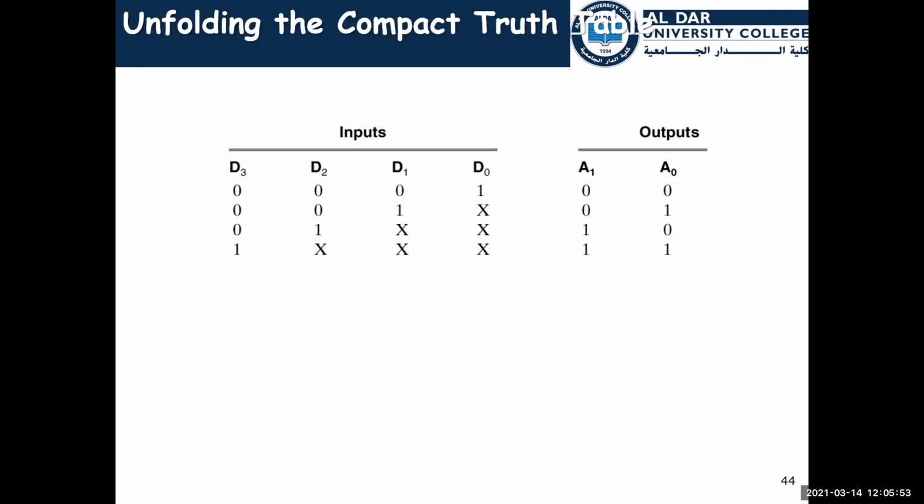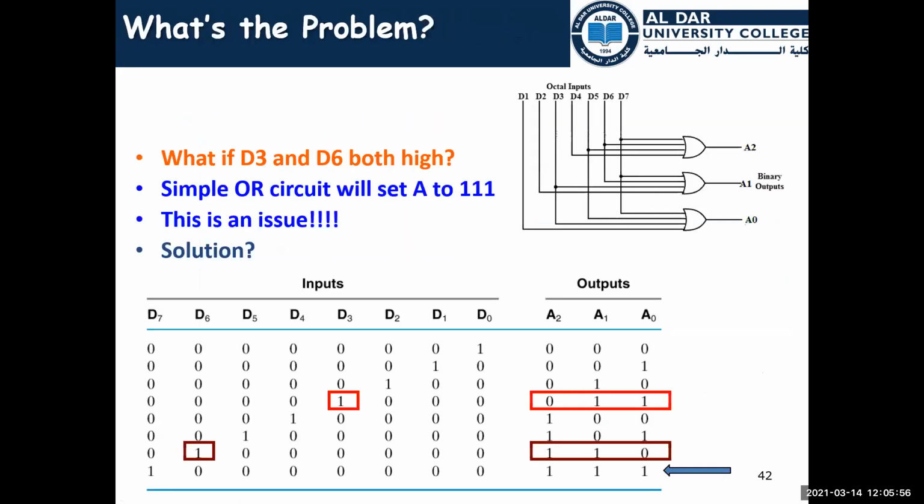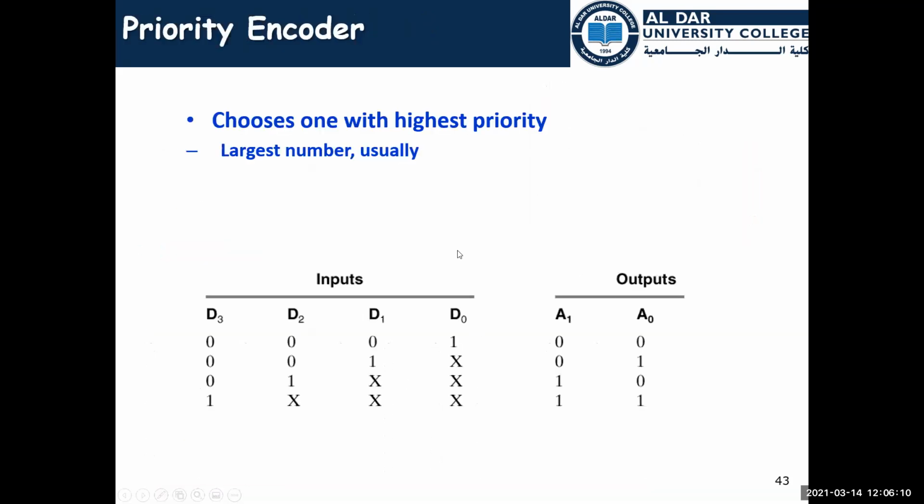I just want you not to cut what you are doing. I want to make a priority encoder. I started by expecting multiple inputs to be one. Then I said I have to solve it using priority. So I put don't care for the other terminals. If one of them is one, the others will be ignored.